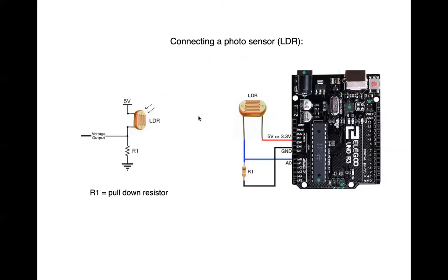We have a very similar case in this one. So it's a very simple sensor, which is a photoresistive sensor, sometimes called light-dependent resistors, LDRs. They are simple resistors. Their resistance changes with the light illuminated onto the sensor. So the resistance actually decreases as the light intensity increases, resulting in a higher current flowing through the circuit.